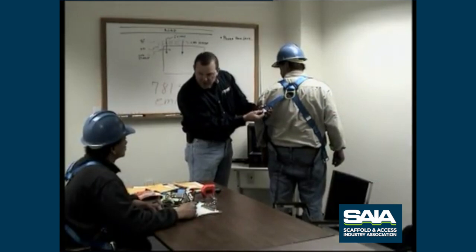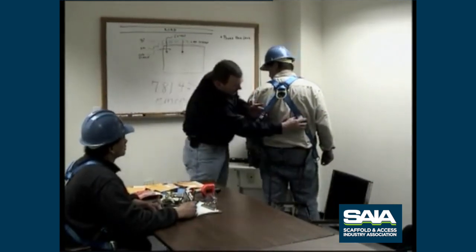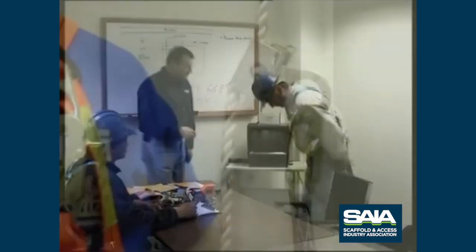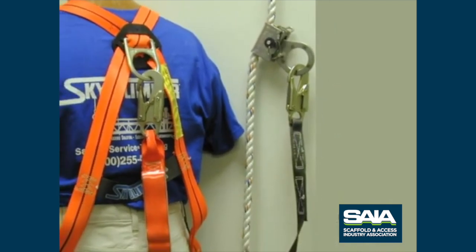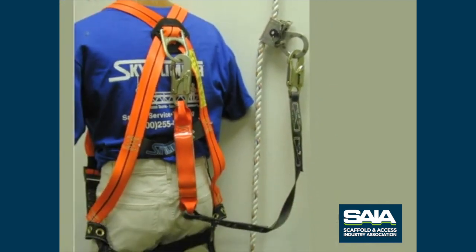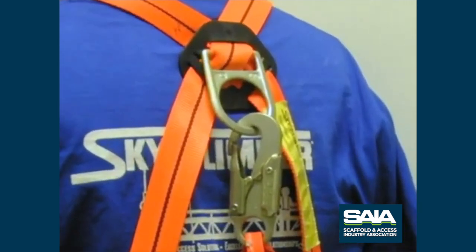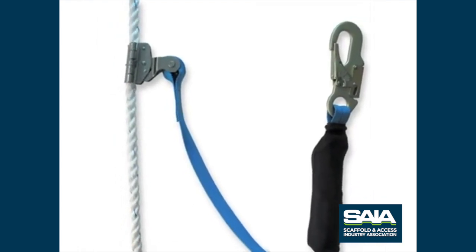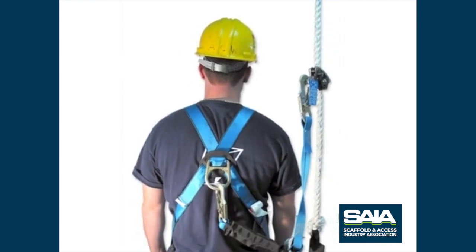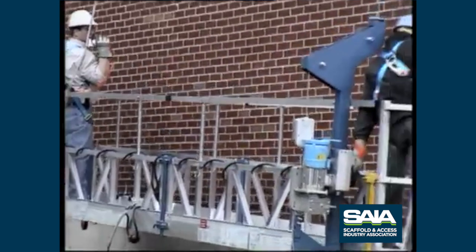All harnesses, lanyard hardware, lifelines, and anchorage points must meet the requirements of the codes applicable to the jurisdiction where the work is being performed. Lanyards must have double locking snap hooks or be spliced directly to the fall arrestor. The harness D-ring is located between the shoulders of the body to minimize injury in case of a fall. Shock-absorbing lanyards must limit free fall distance to less than 6 feet. They must be connected to the rope grab device above shoulder level. Following this practice will minimize the distance traveled and the severity of the injury should there be a fall.